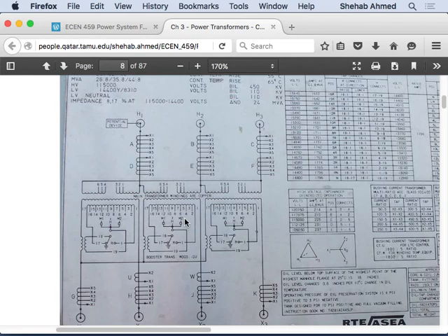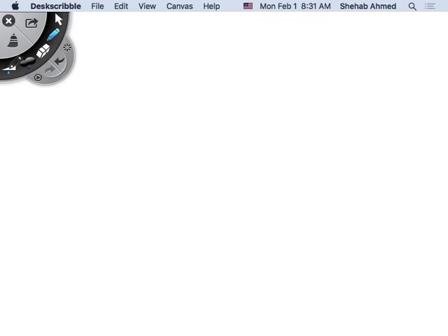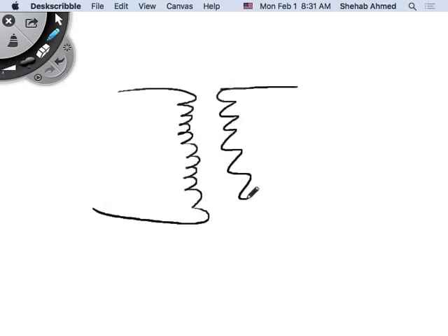So one way to change the voltage around the system will be through adding capacitors. Right? That's one way. The other way is what? Is transformer tap changing. Right? A transformer tap changer basically does this. You have a transformer here, primary and secondary. Instead of feeding the secondary, for example, from these two windings, you feed it from what is called a tap. So you're actually physically connecting to this winding. These windings will be physically available for you to connect to.